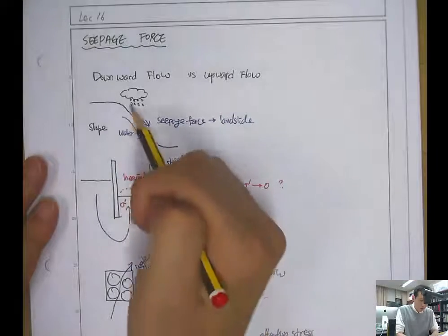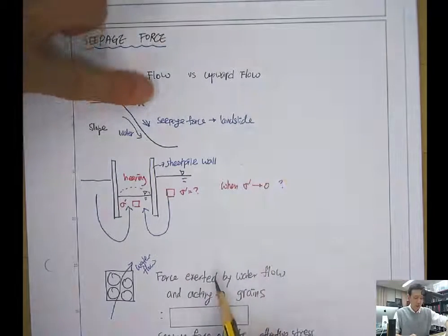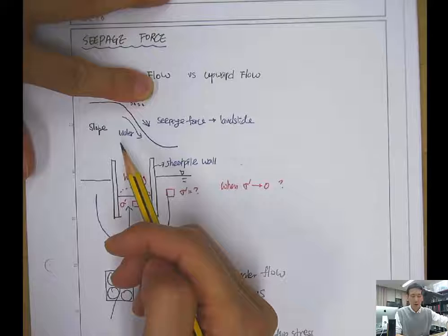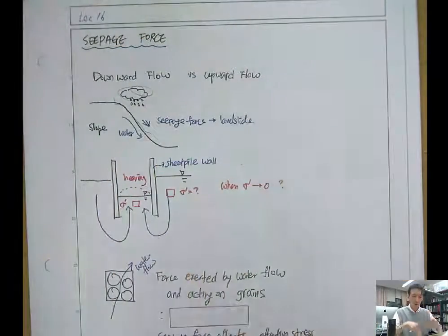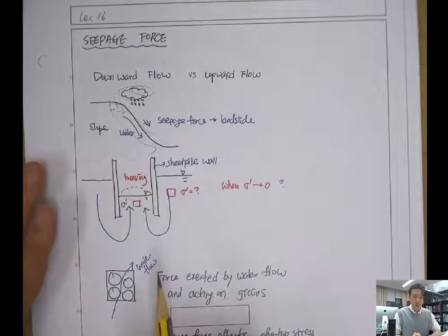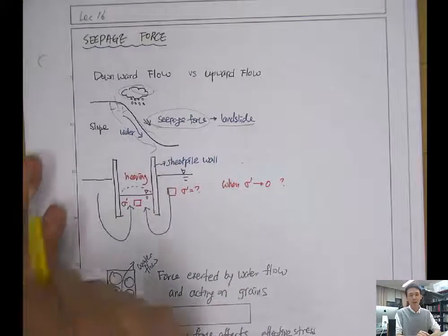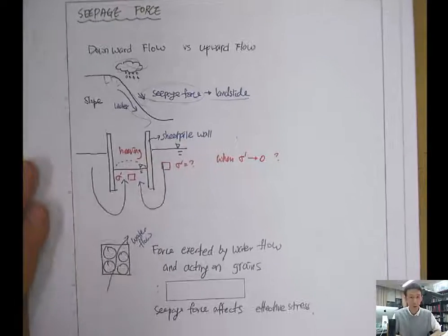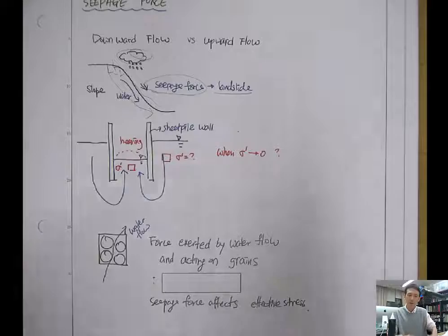When there's no rain, the slope is stable, like as we cut it. And when there's rain, the water flows over the ground surface and also infiltrates into the soil, and it can flow because of gravitation. This downward seepage flow often causes landslide or slope failure. So we can imagine that the water flow has some mechanical effect, as an external force on the soil grains.